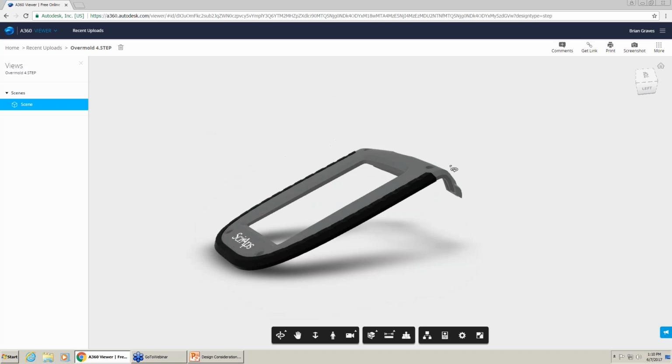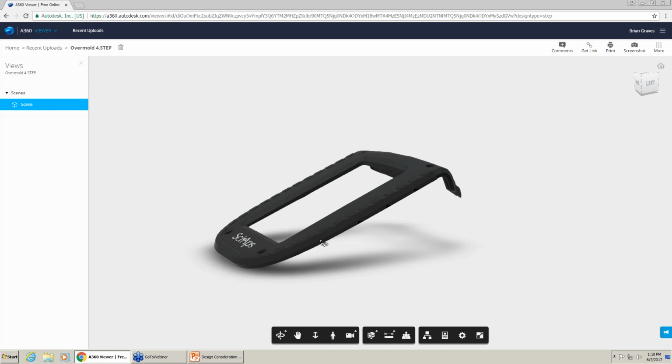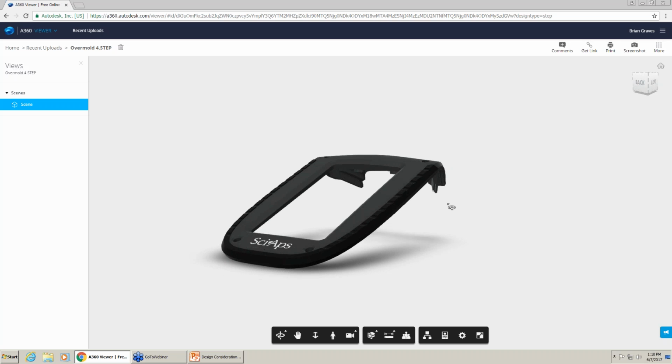And literally this is designed so that when this housing goes together, it creates just an extra feature. This could be aesthetic, this could be a cosmetic feature as well, just to add in something that looks different. But also it blocks the parting line that goes all the way around this part, makes it look very clean and seamless. This could have a couple of different functions as far as how this part is used in the end product.